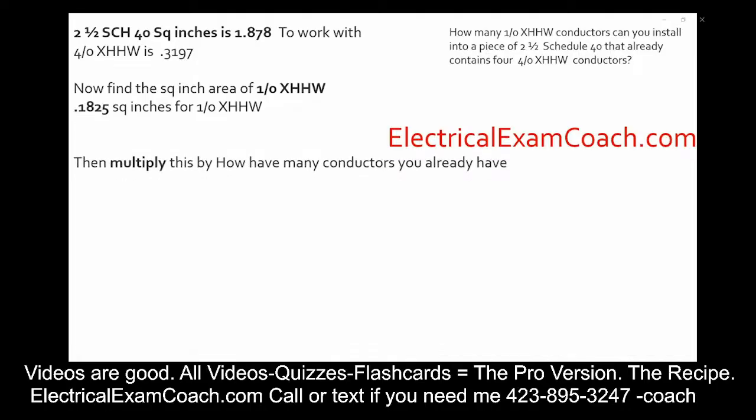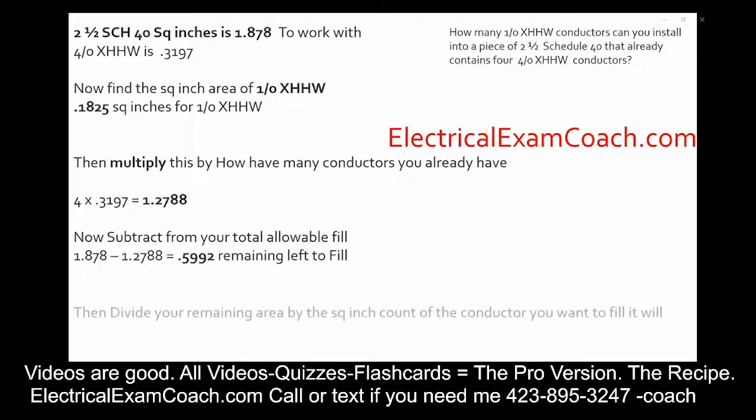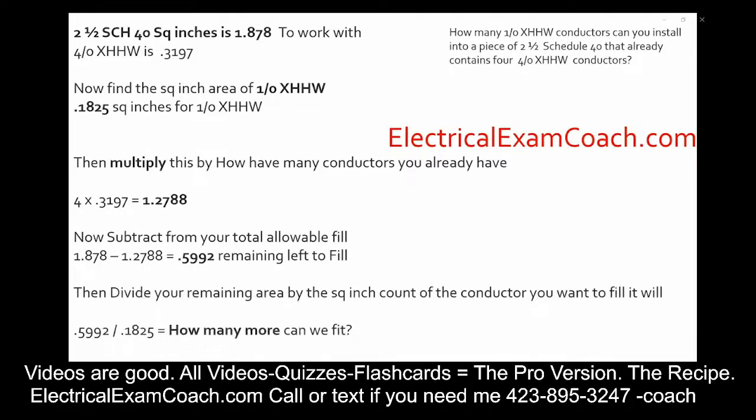We multiply by how many conductors that we already have. We have 4 multiplied by the value for a 4/0, and that gives us this number. Then what we're going to do is take our total area that we were able to fill and subtract what we have, and that lets us know what we have remaining left to fill. Then all we have to do is divide. We take our remaining left to fill, divide by our individual 1/0, and that lets us know that we can fit 3.28 conductors. We are below 0.8, so we're going to round down, and we find that we can fit 3 more in the conduit.